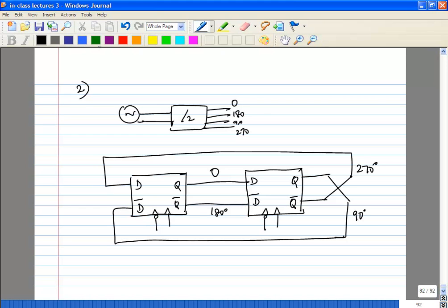Of course, you need your input frequencies. The clock inputs get the VCO signals. So obviously the VCO needs to be twice the frequency of your LO frequency. If you are designing a transceiver which is going to operate at, let's say, 1 gigahertz, your VCO will have to operate at 2 gigahertz at least.